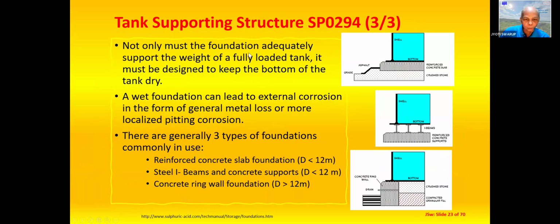Not only must the foundation adequately support the weight of the loaded tank, it must be designed to keep the bottom of the tank dry. This is the most important criterion. A wet foundation can lead to external corrosion in the form of general metal loss or localized pitting.